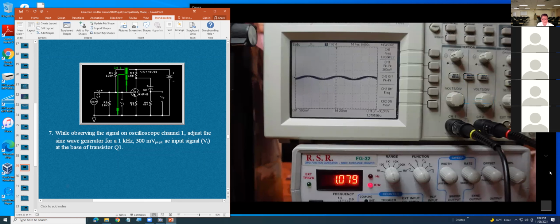Now, I get another question. If I want 100 millivolt peak to peak, what can we do? Either 100 millivolt or 50 millivolt peak to peak. The generator cannot do it. Are you saying you need to adjust your circuit for some type of voltage divider? Somehow. You're telling me, if I want 100 millivolt peak to peak, the generator inputs through the attenuator and then the outputs in.